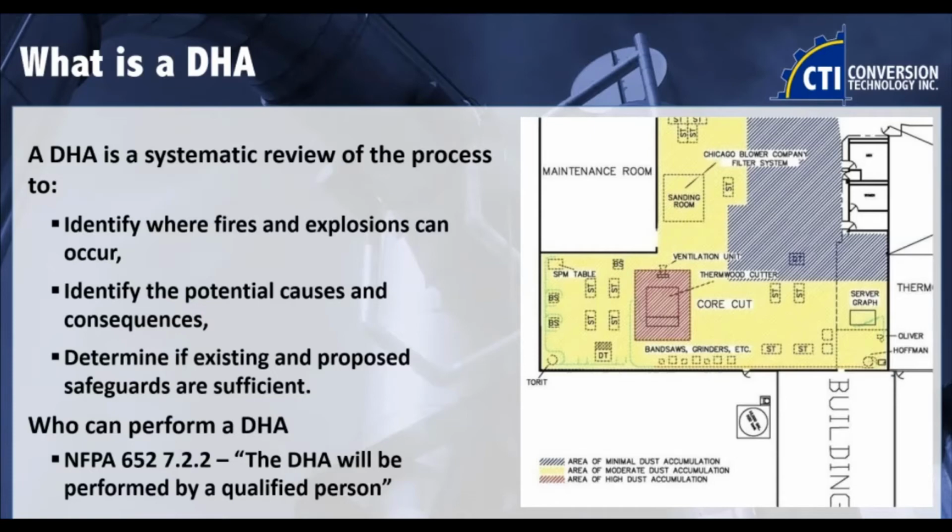So as I mentioned, NFPA 652 states that a DHA will be performed by a qualified person. That is what it says. So if you go to the definition sections of 652, it defines a qualified person as a person who, by possession of a recognized degree, certificate, professional standing, or skill, and who by knowledge, training, and experience has demonstrated the ability to deal with problems related to the subject matter, the work, or the project.